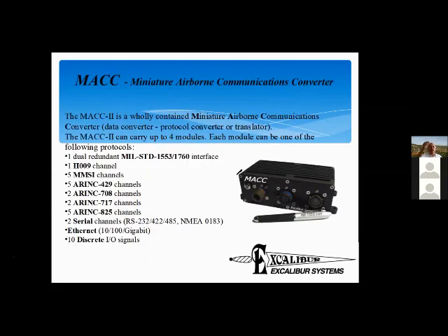Okay, now a final word on something which there's been a lot of interest in recently, which is a translator. Very often what you'll have is that you've been used to using a particular military bus or any kind of bus, and you've got to change for some reason or other. Now, we've had this, for example, on helicopters. Right, so a helicopter, if it's a civilian helicopter, it's very likely to have a lot of ARINC 429. If it's a military helicopter, it's very likely to have a lot of MIL-STD-1553.